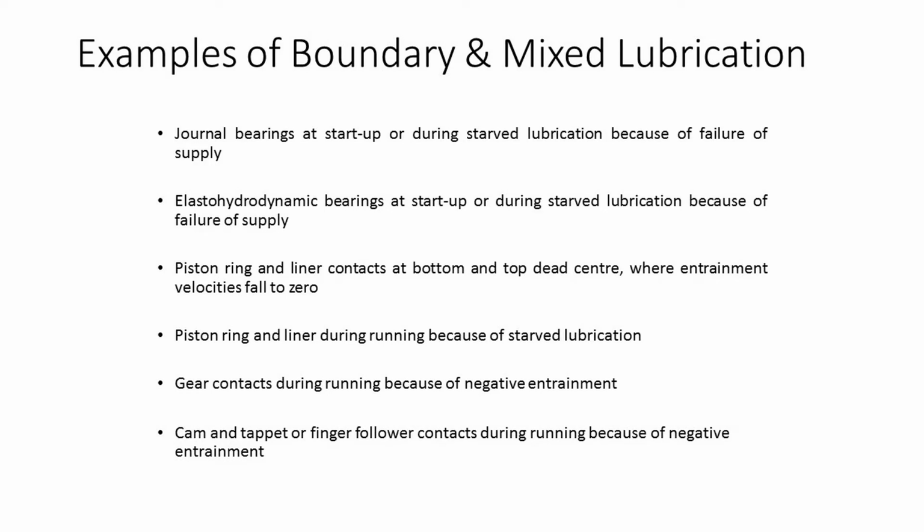In the cases where we cannot prevent intimate contact between the mating surfaces, we have to rely on lubricant additive chemistry or coatings to limit wear of the surfaces and to provide protection against scuffing, which is the onset of adhesive wear. It follows that, excluding the special case of rolling contact fatigue, all lubricated wear testing is focused on modelling contacts that are operating outside the hydrodynamic or elasto-hydrodynamic regimes. Under these conditions, lubricant viscosity plays little or no part, and the performance of the contact depends crucially on the lubricant additive chemistry.